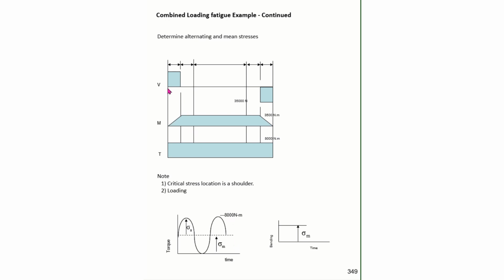We can see that our shear force here jumps up and then drops back down to 0, comes over, drops down, and then jumps back up. So our moment diagram would jump up to a max, remain constant, and then drop down. And we would have a torque that would jump up, come across, and drop down. We can also draw the load diagrams for the loading on the shaft. And I would encourage you to draw these load diagrams because they really help understand the problem.